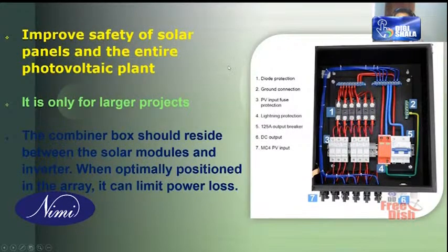So DC wire is normally considered the low voltage side, and AC is the higher voltage side. So low voltage means, for a given power, your current will be more. So current will be more means IR drop will be more, and I squared R loss also will be more. So it is always better to reduce the DC line. So you connect the AJB as close as possible to the solar module. Okay, so that will decide how optimally we can use the solar power.